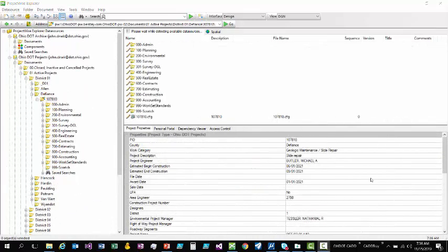The only other difference is where you put your workset config file. So outside of ProjectWise, I showed you copying that template config file and pasting it wherever you set your config file location to be. But inside ProjectWise, you're actually going to paste it inside your work set folder. So I'm in here, I already have it here, so you would copy and paste it and then rename it to match your work set name. But like I said earlier, you don't have to edit the file inside ProjectWise. It's all set up and ready to go.